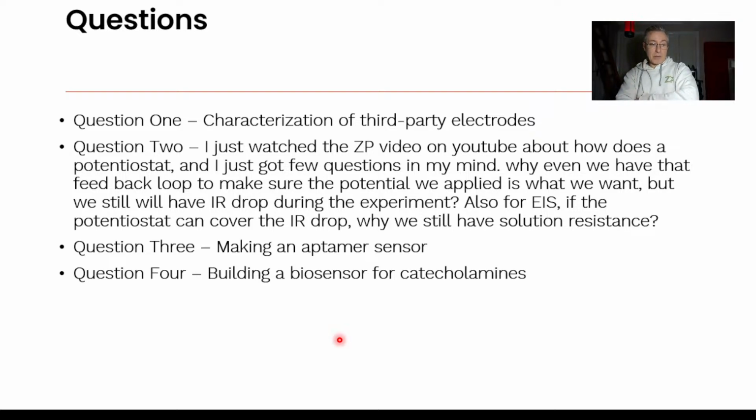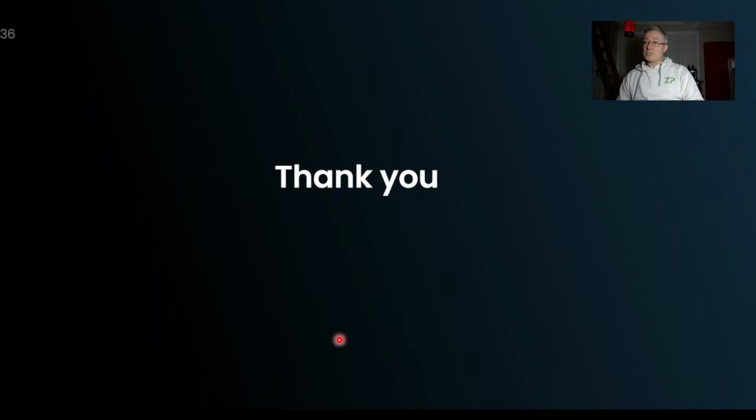You can use carbon as well as gold. Your PEDOT:PSS is peeling off because there's no real reason why the PEDOT:PSS should actually adhere to the gold. It'll probably adhere if you made it a thinner film, or maybe if you went to a carbon electrode. I think carbon's actually not a bad material. And in your program, you're mixing two things. You're mixing fabrication of the electrode with building value on top of the electrode. You need to split those two things and then bring them together at the end. And that's more of a strategic comment.